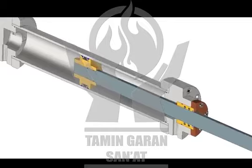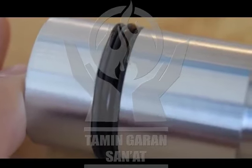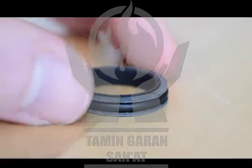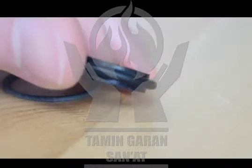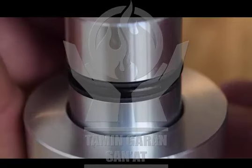In a dynamic application, O-rings can work, but there are much better options to consider. This is called a T-seal, and they are specifically designed for dynamic applications. They are packaged with 2 backup rings as a unit, and their primary advantage is that they have a wide, flat bottom to keep them from rolling around in the groove. They don't cost much more than O-rings, and in our experience, are very reliable in dynamic applications.